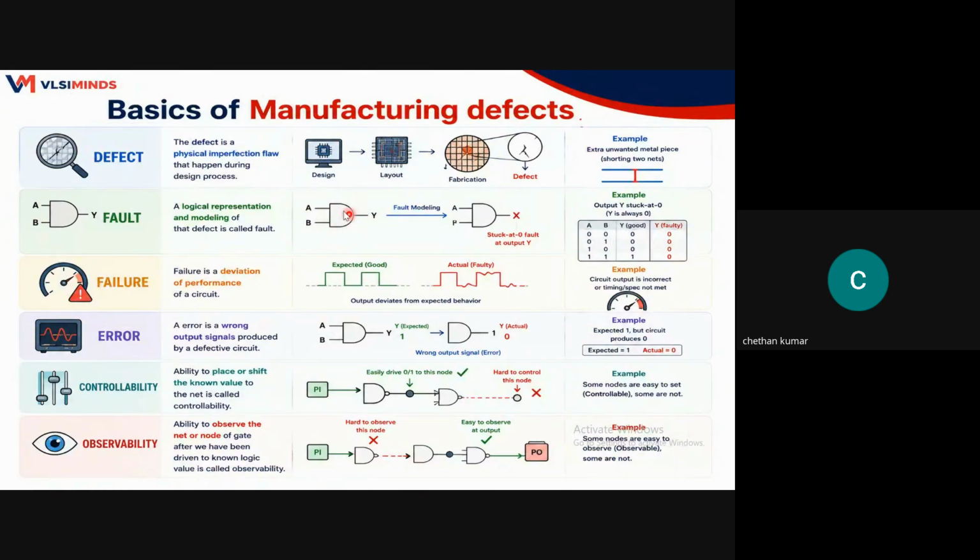But this AND gate is placed among millions of transistors or millions of gates, one among the millions of gates. How do I get controllability? It's not so easy, right? Finding that particular gate and then saying that it is defective. For that, I need some strategy to test this design in a structured way. So I need to go with DFT logic. Is it clear for everyone?